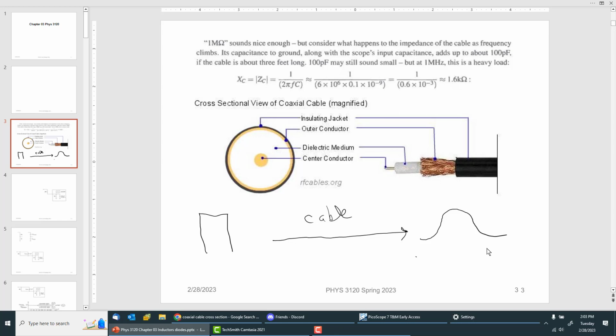The coax they used in the beginning with the Ethernet was so-called thick coax. It was like 3/4 of an inch in diameter because, if you recall from Physics 2100, even in this class, capacitance is area over separation. So the separation is in here. If you think about it, these are two parallel conducting plates, being coaxial like that. And so the dielectric medium is chosen to have a low dielectric constant, not a high one.